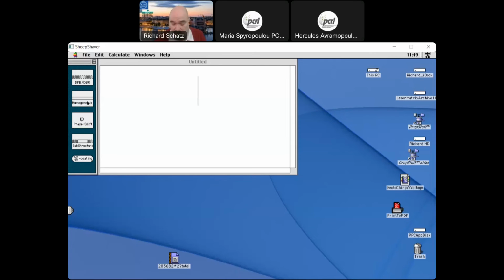So let's start to make a simple Fabry-Perot laser. So I just enter here the material, the length, the current over threshold current density, the waveguide loss, and yes, this is if you want to change the index.